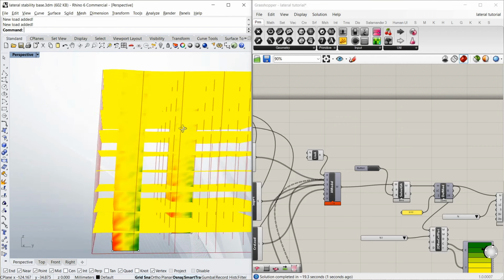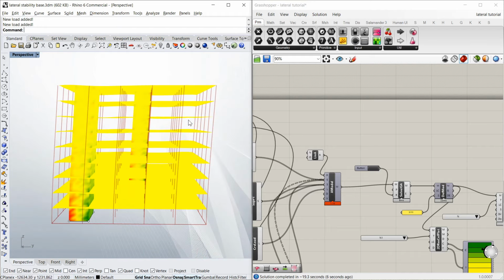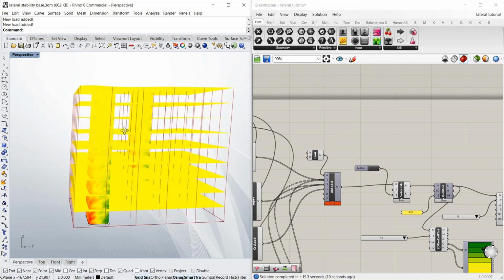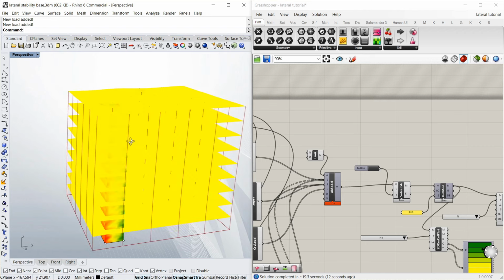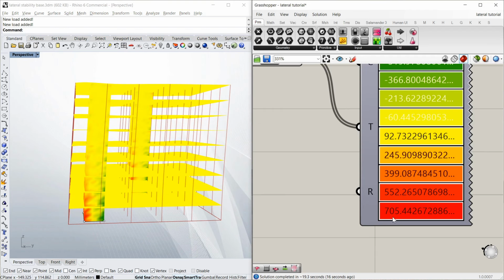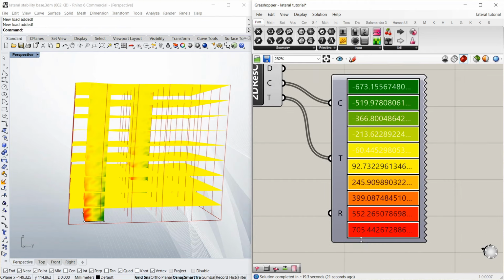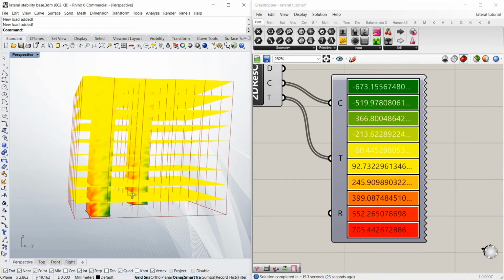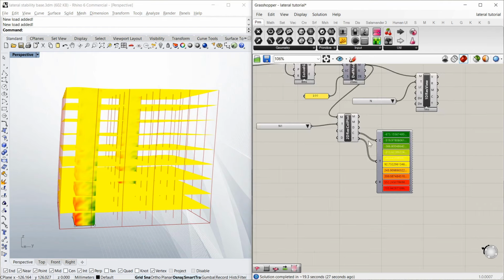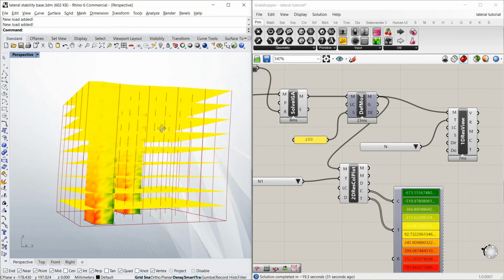There you go. And if you remember, it's a lot less horizontal deflection in this model with 2 cores than it was with 1. And we've got a lot less stress as well. We had 1800 or 1900 before, now we've only got 705. So that's just a very, very quick way to get a feel for a building.